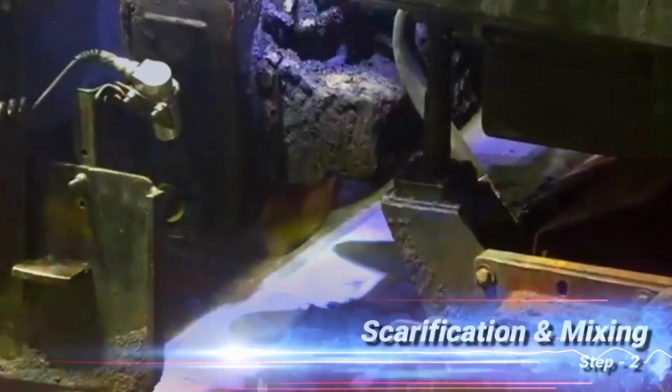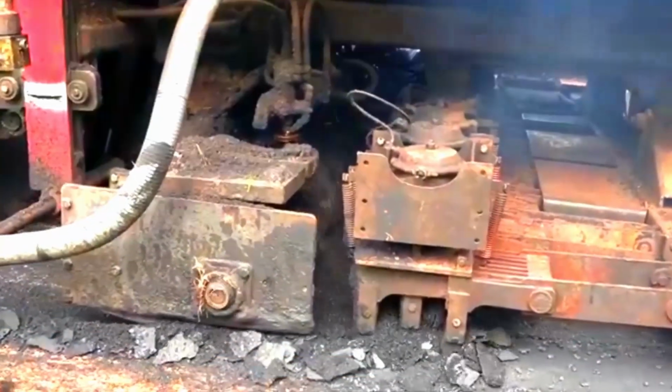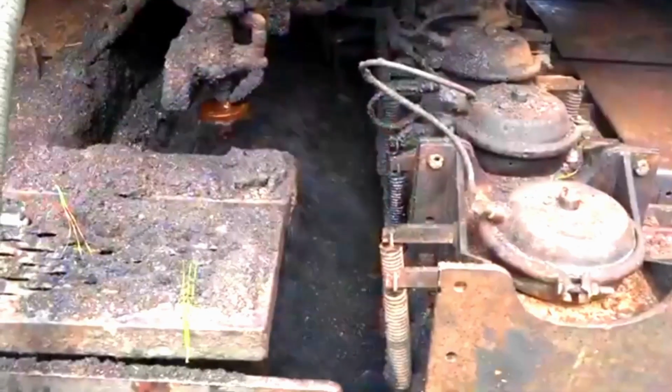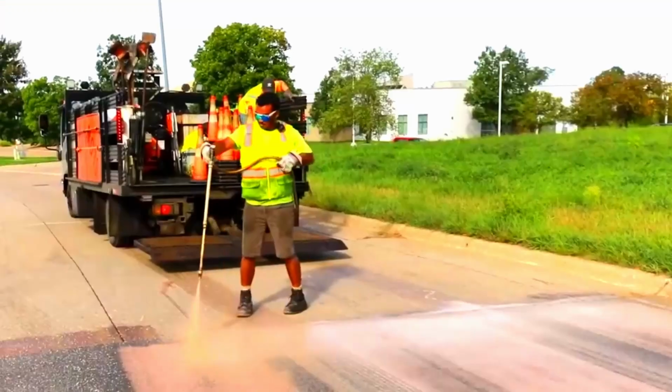Step 2. Scarification and mixing. The softened asphalt is scarified, loosened, and mixed with new bitumen. Anti-aging rejuvenators may be added to restore lost flexibility in aged asphalt.